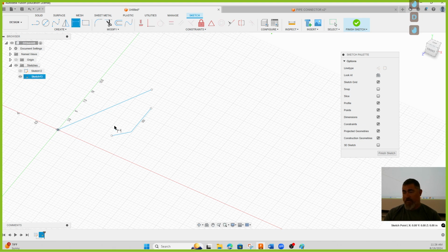If I pick 2 points, it's the same thing. I can do horizontal between the points, aligned, the distance straight between them, or vertical. So if I have this line, I'm going to dimension this line, it's a lot easier just to pick the line than it is to pick the 2 points. So just pick the line.